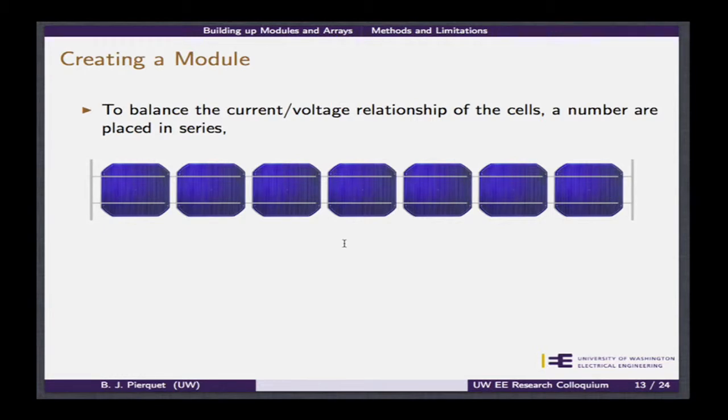And so that particular area is going to determine what current it can put out. And so in this case, they're sort of stuck. They're at 6, 8, 10 amps, depending upon the material, just given the size they're at. And so in order to get more power out of a module, you increase a whole bunch of them in series. So you basically connect them in series.